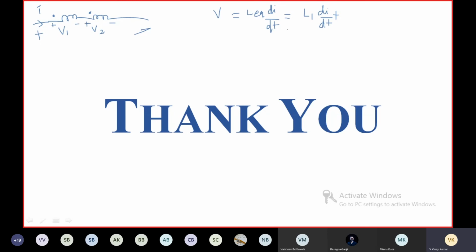First, L1 di by dt is the self-induced EMF in coil 1. Coming to the mutual induced EMF in coil 1, let M be the mutual inductance between these two coils. Here current is entering the dot terminal of coil 2, which means the mutual induced EMF will be positive at the dot terminal. Positive at the dot terminal means you are collecting voltage at this point with respect to this point, so the mutual induced EMF will be M di by dt. So V1 is L1 di by dt plus M di by dt.